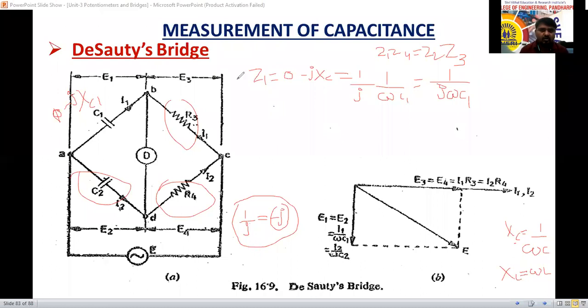Roll number 10 and 12, if you still have any doubt, tell me. This is the last concept of the third unit. We are not going to study this chapter again. If you have any doubts, clarify now only. Let it be late, but your doubt should be cleared. No doubt, sir. So, capacitor C1 is there, directly you have to write Z1 equal to 1 by J omega C1. This is for understanding; all the steps I have taken are just for your understanding. Z1 equal to 1 by J omega C1.